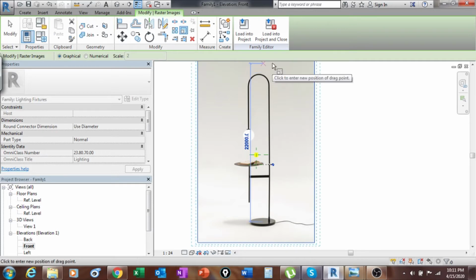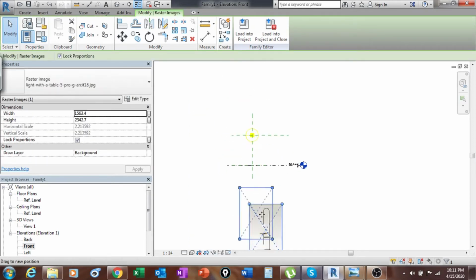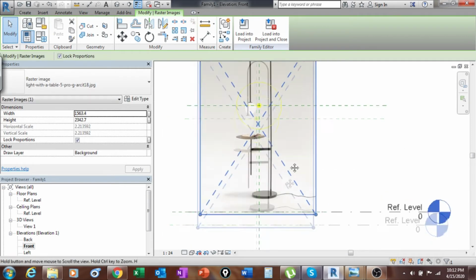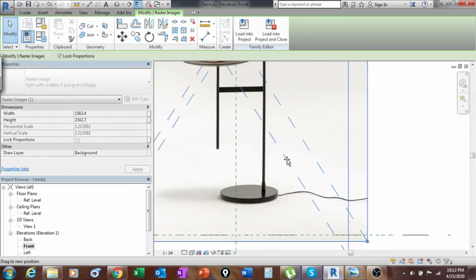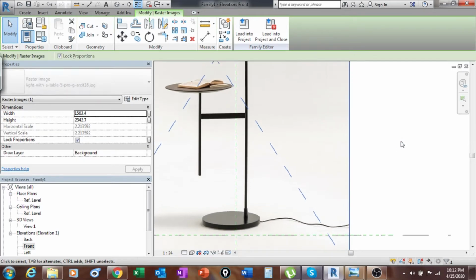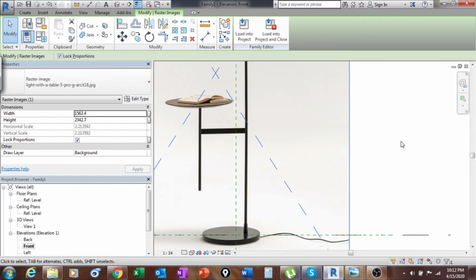I want this to be, and then you need to type it, 1,900. And scale is pretty similar for those that are familiar with AutoCAD. It's pretty similar to scale with reference in AutoCAD, in which you show first this segment, and then you tell Revit basically how long you want this segment to be.